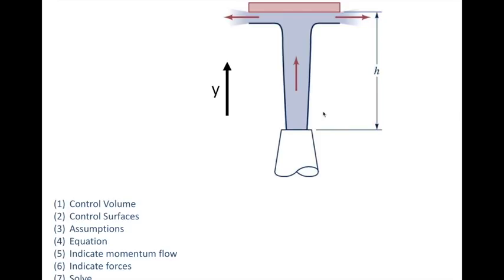Keep track, think it through. How are your pressures changing? How is your momentum flux changing? And how can you break those up into what's happening in the x direction and in the y direction? What forces are acting on this entire control volume?